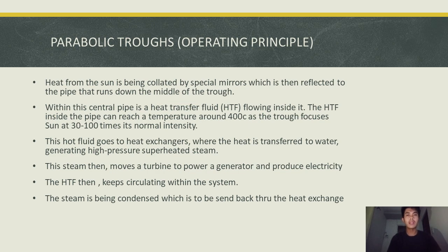The secondary winding is linked to a measuring device such as a voltmeter or wattmeter to measure the voltage or power in the circuits. A magnetic field is produced around the primary winding when a high AC voltage is applied to it. This magnetic field induces a voltage in the secondary winding. A large number of turns of a conducting wire are built into the secondary winding, which aid in stepping down the voltage to a lower level.